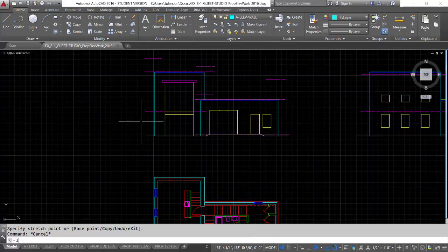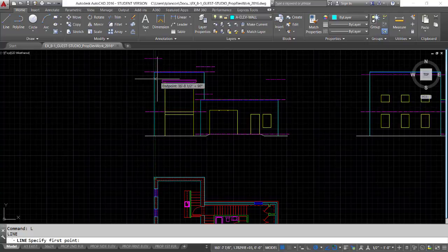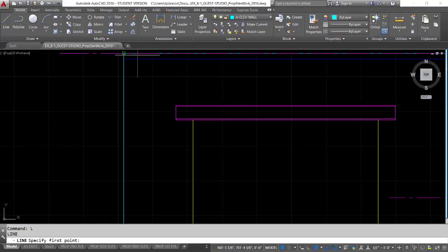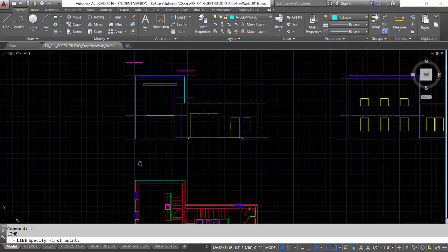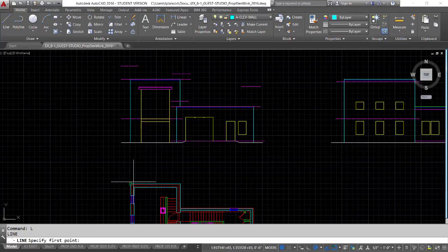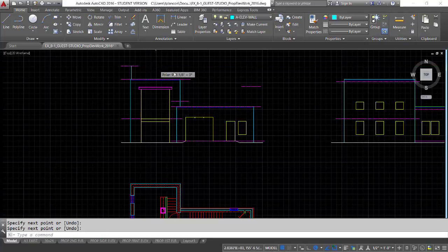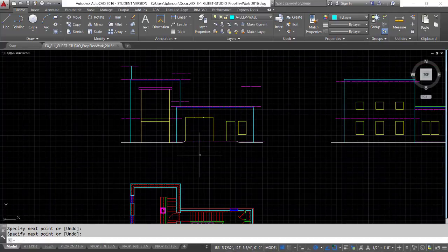Let's start the line command, and let's go down here and acquire a point. And again, I have to use the shift key to do that. So shift, drag that up until it hits. Oops, I zoomed, so that loses my tracking. All right, let's try that again. Hover over the corner point, shift to acquire, drag up till I hit the intersection point, and then click, and then come up until I hit my guideline there. And then the same on the other side.